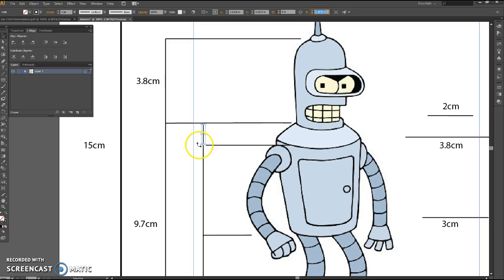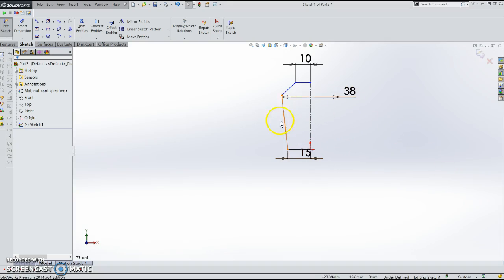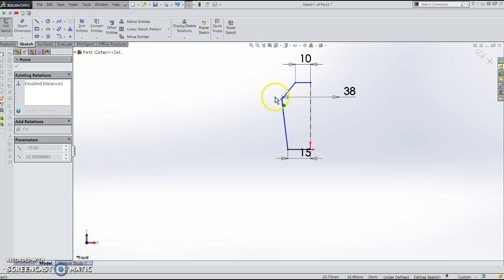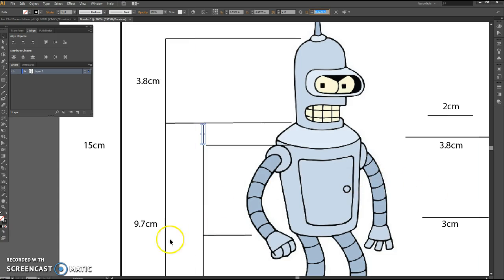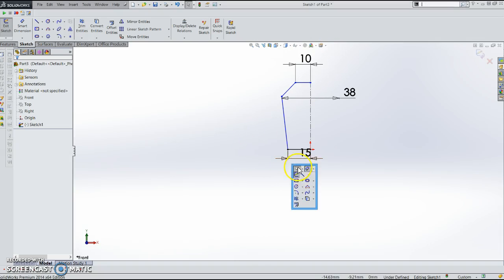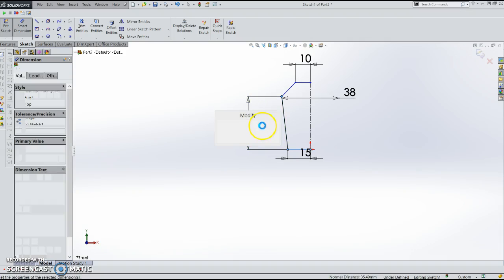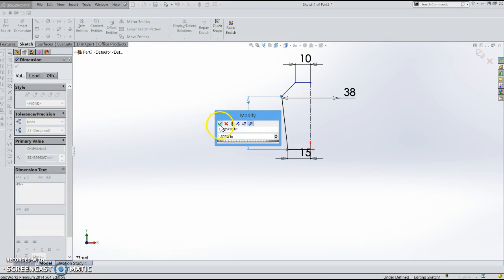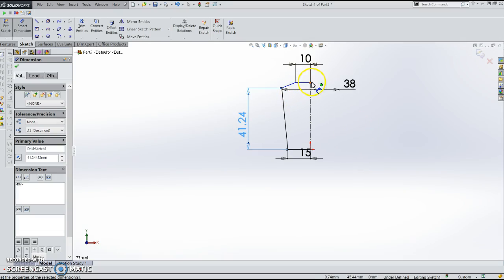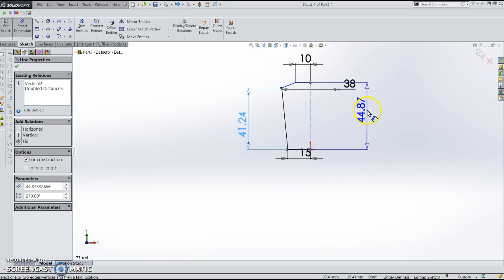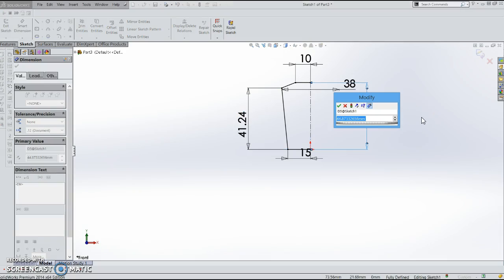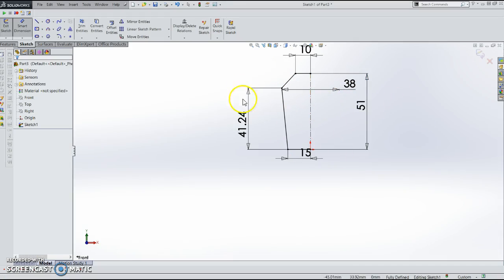Just double check this. Okay. And then the height of this, I'm not sure, so what we'll do is double check that. What it was again. Copy. Dimension on here. Paste that in. So the overall is too short. It was 5.1 centimeters. There we go. So the sketch is all black, just what we need.